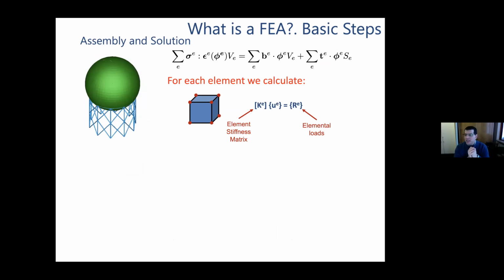Okay, a vector of elemental loads, which is associated to basically the external loads that are applied to that particular element. And in the case of nonlinear analysis, it is the difference between the internal and external forces, and a vector of nodal displacements, element nodal displacements. For an elastic solid or a deformable solid, the element equations can be compared to an elastic spring, in which the matrix KE is associated with the stiffness of the spring, and RE is the force that we need to apply to deform the spring, U sub E, UE.